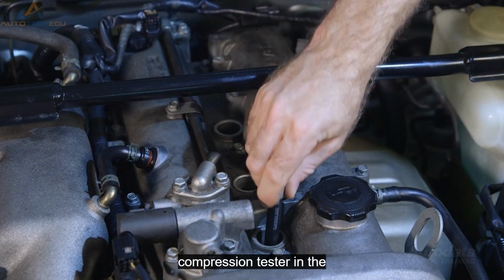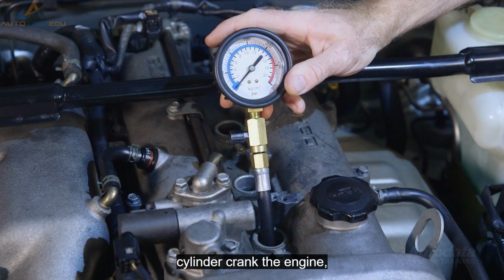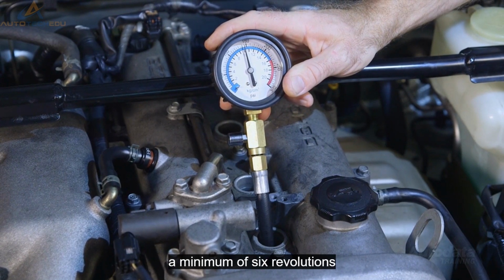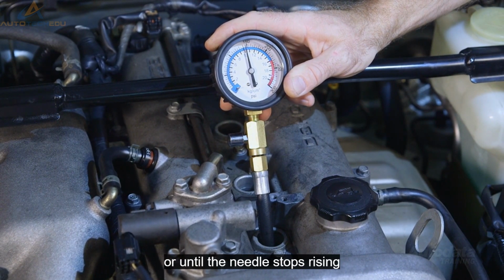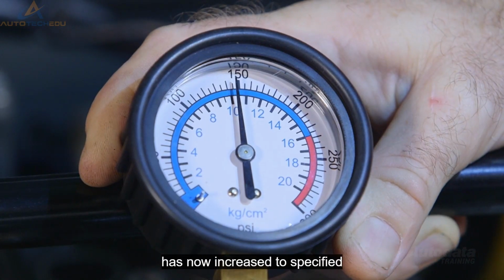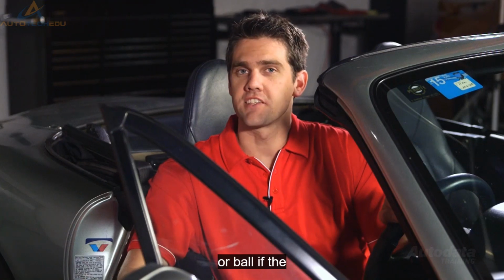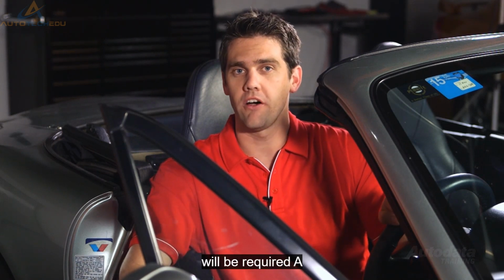Reinsert the compression tester in the cylinder. Crank the engine a minimum of 6 revolutions, or until the needle stops rising. If the cylinder pressure has now increased to specified levels, the fault will most likely be the piston rings or bore. If the cylinder pressure doesn't increase, then a leak down test will be required.